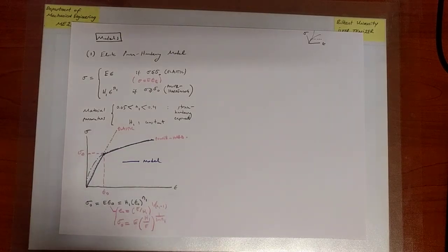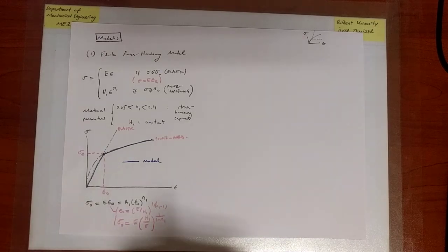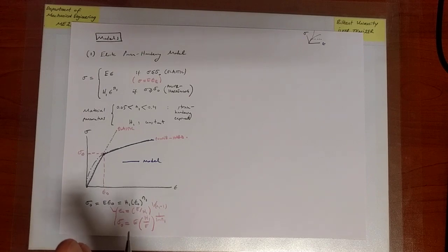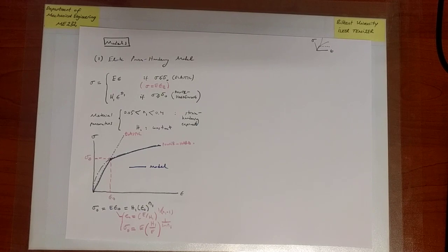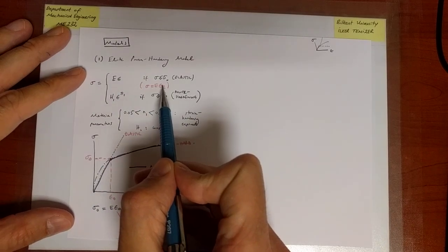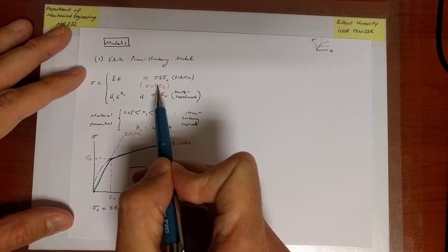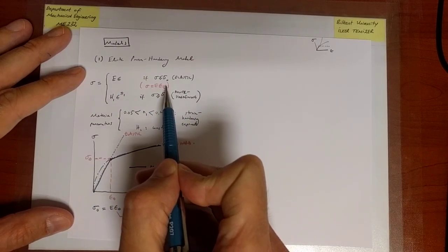Now, the second thing I'd like to comment on is the question of what the plastic strain is. Earlier, when I was talking about the modeling aspect, I said that what we really want to implicitly address is what the value of the plastic strain is, because sigma is always equal to E times epsilon E, and epsilon E is the total strain minus the plastic strain.